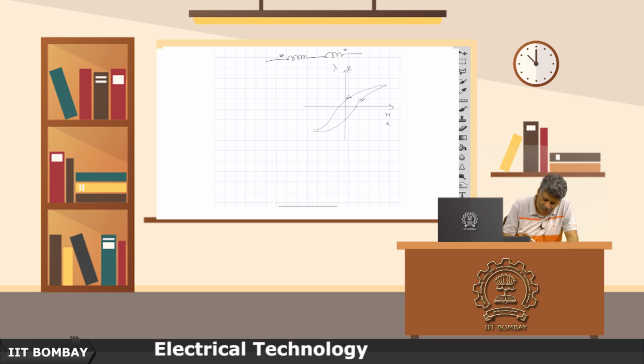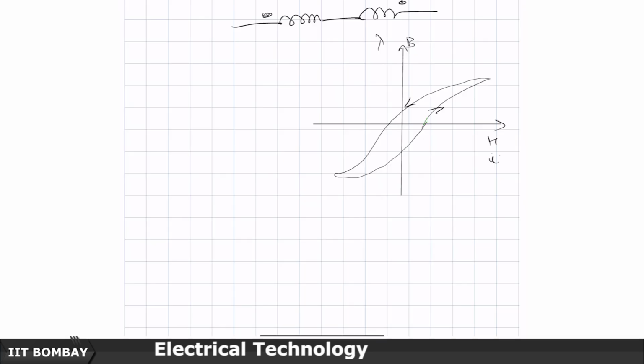So, we had discussed earlier that if this has been repeating for a long time, it will settle down to a hysteresis cycle like this. Let us say we start from this particular point where the B is 0, and to get that B we have applied a current I. This is the remnant B in it, once positive, once negative, and these are the coercive forces which are used to cancel whatever is the existing B, which here was negative. So, the magnetic dipoles were aligned in the opposite way. We applied positive current to it, and gradually they got de-aligned and became random, after which they started realigning and increasing the B, and so on. So, we have understood this earlier also.